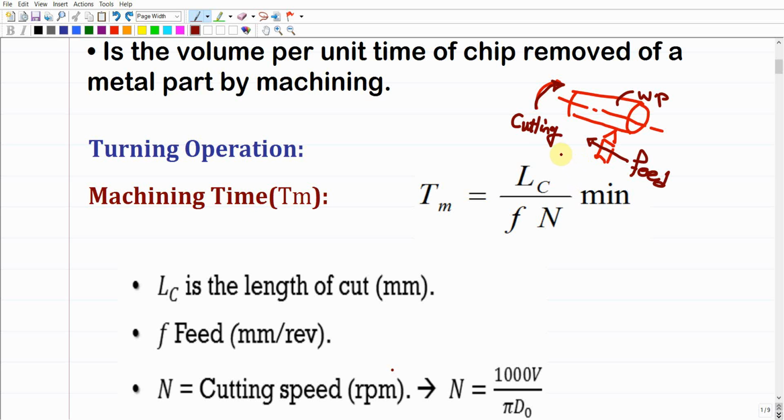It means that the transmission system inside the machine, if you had a chance before to look at the transmission system of the machine itself, you're going to find that the gears that create the cutting speed and the cutting motion are connected to the gears that produce the feed motion, or the mechanism of the feed motion is connected to the cutting motion, and they transmit the power and the motion to each other.